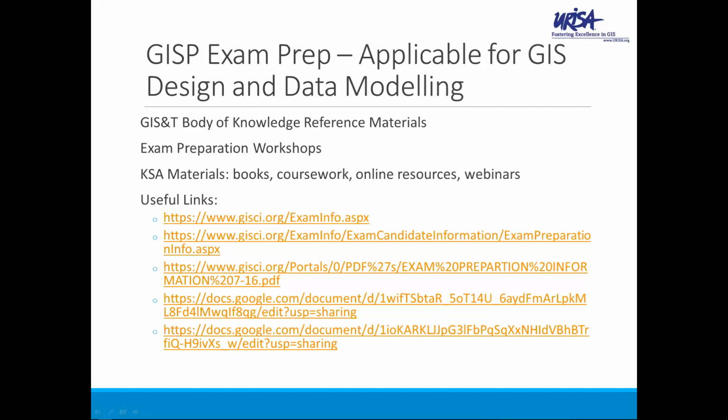Somebody wants to know more about the triangular and object-oriented models. Yes, so a triangular irregular network is often used for terrain modeling, and if you look at it, the data looks like little triangles that join together and actually create a surface.